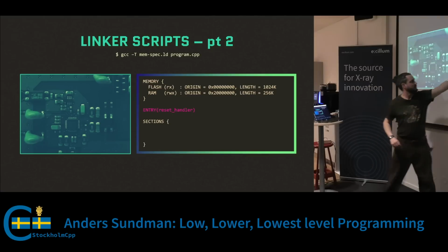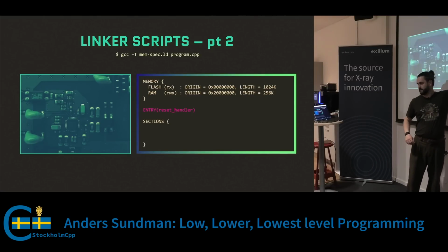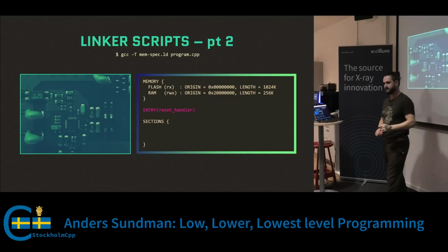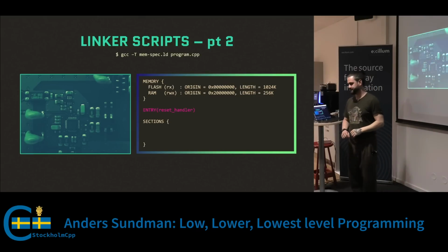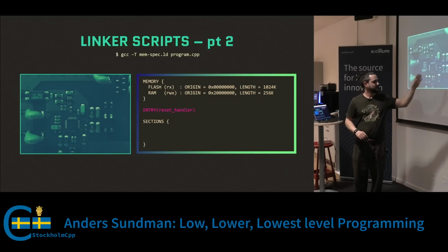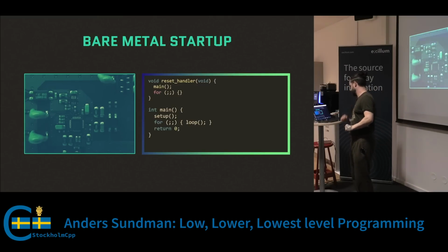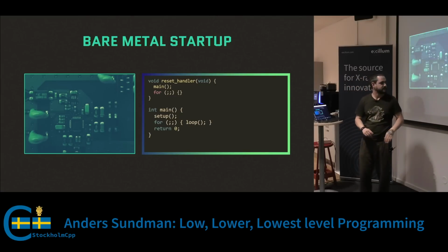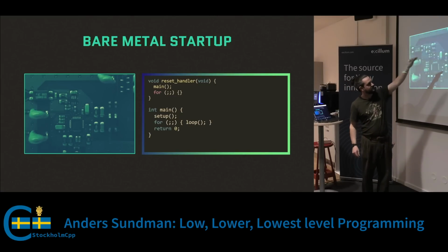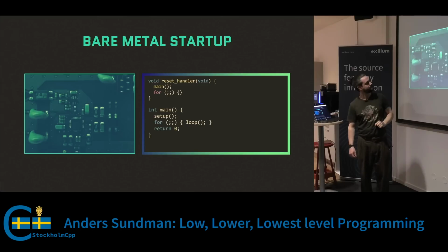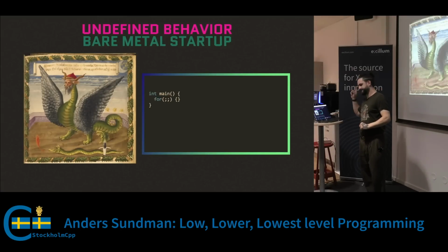If you do this, it will not start with _start. It will start with this thing. And then you have to call main yourself. So let's assume this deals with how it gets called, and we will get back to that as well. This is just what we have. We have the reset handler, and we have the main function with the firmware super loop.